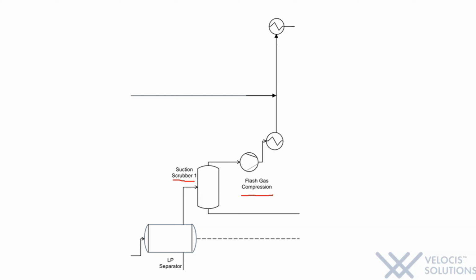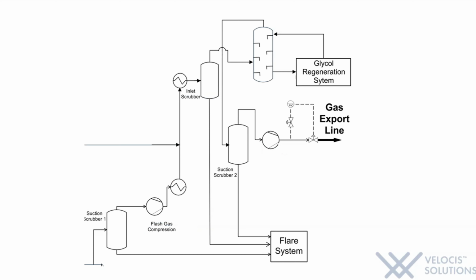However, immediately after going out of the compressor, the vapor enters the cooler to give its excess heat away prior to joining with the HP vapor. Once these vapors are mixed, they once again get into the cooler for further removal of heat down to 16.12 degrees Celsius. Unfortunately, all of the cooling procedures result in the creation of liquid particles inside the mixture.